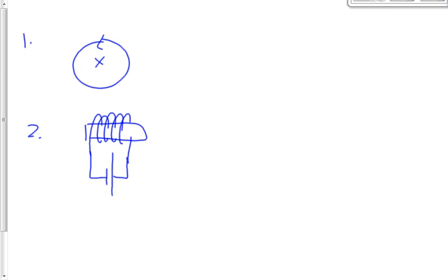So in this case, we'd say, look, my current is going from the negative side to the positive side. It's going clockwise around this coil here, around this solenoid. We'd stick our fingers up in the front. That would mean our thumb would automatically point to the right. That means that inside the coil, the magnetic field is pointed to the right. This would be the North Pole. This would be the South Pole. Again, Wire-Grasp rule, thumb, fingers. Coil rule, fingers, thumb.